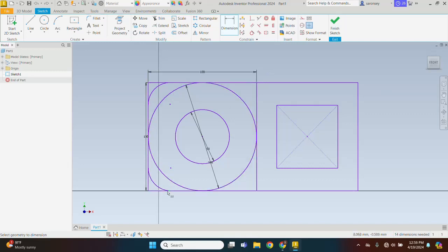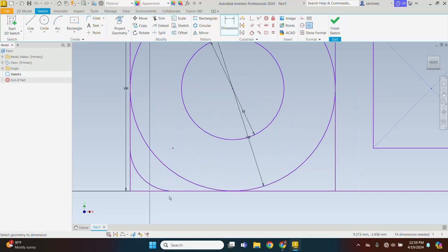We place the arc anyhow, but now we want to specify the actual start point of our arc. So this was where I think we began to draw. If you hover your mouse here, you see the green dot. It allows us to select the end point of that line. So we click there, and now we click here where we started to draw our rectangle.